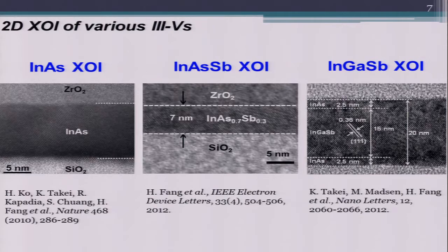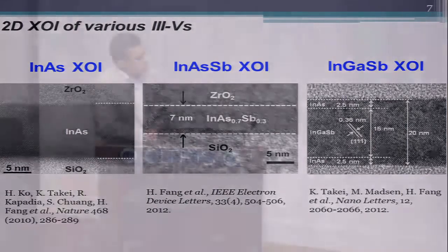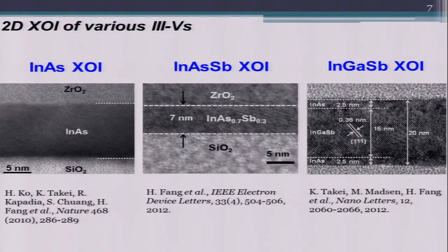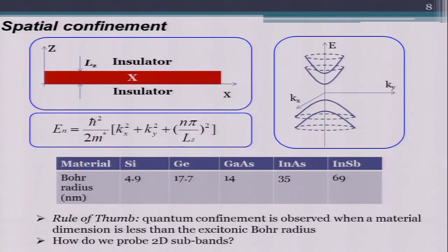And the second question was, we're dealing with very small bandgap materials. We were at one of the funding agency reviews, and we were told that indium arsenide is the wrong material system. The bandgap is too small. The bulk bandgap is only 0.36 electron volt, and that's not enough for getting low leakage currents. And of course, the answer to that was quantum confinement. You cannot think about the bulk band structure, but you have to think about the band structure for the membranes, for the materials that you're dealing with, down to the thicknesses that you're playing around with.